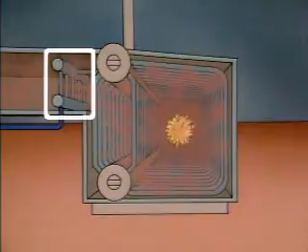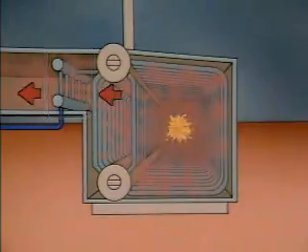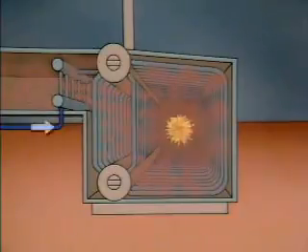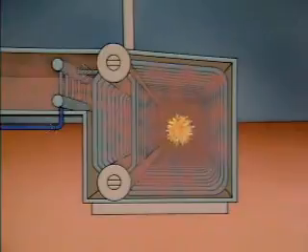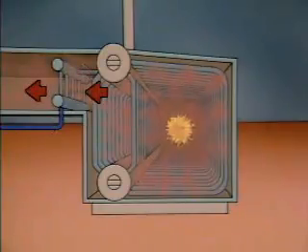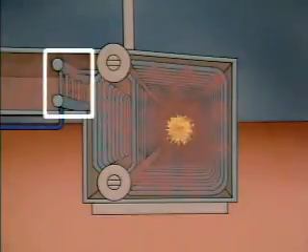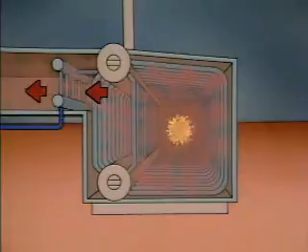An economizer is basically a series of water tubes located in the flow path of the combustion gases. Feed water is routed through the tubes on its way to the steam drum. The water is heated by the hot combustion gases flowing past the tubes. The economizer improves boiler efficiency by making use of heat in the combustion gases that would otherwise be wasted.